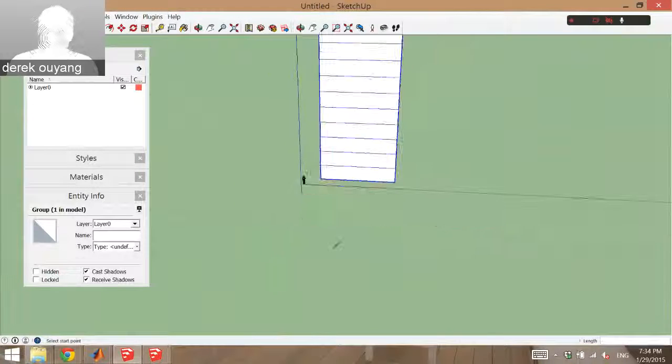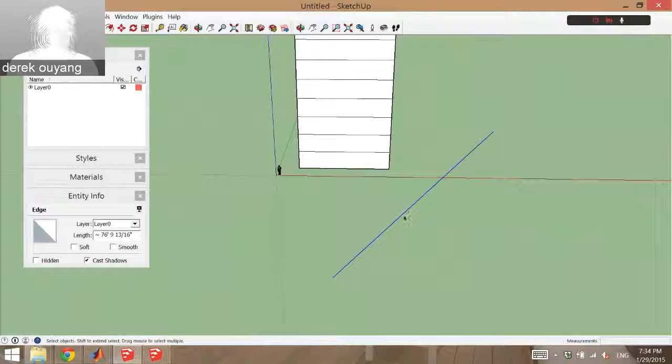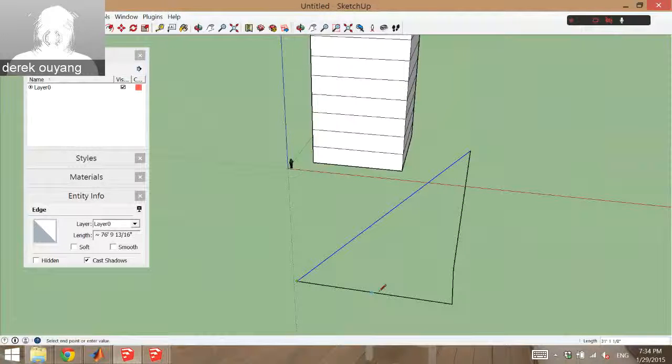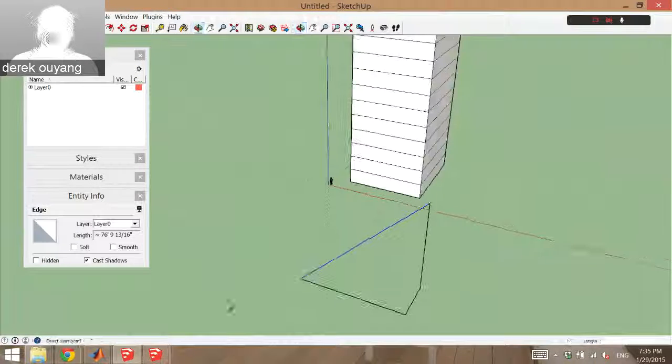And you can imagine this is especially useful. Let's say you have just a crazy line like this. Like let's assume you had to somehow input this 3D object into MASTAN. Then all you have to do is lock to the red axis, go to the edge, lock to the green axis, go to the edge, and lock to the blue axis and go to the edge. And then the dimensions of these lines is what you input into MASTAN, right? Because it's basically on a global coordinate system. So keep that in mind as a really handy way to do this: you don't even do any calculations, just read off SketchUp when you're going back and forth.